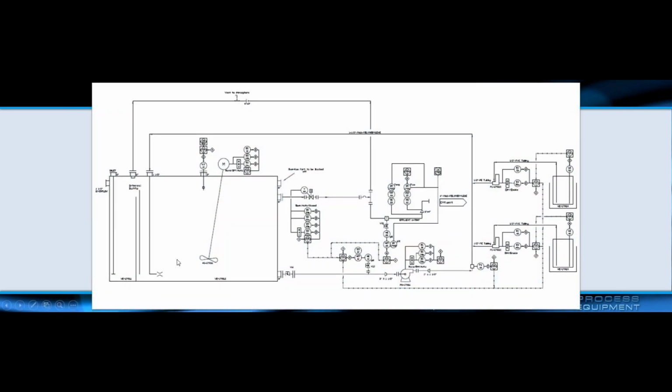Looking at a P&ID here, waste comes in. Sometimes you have a small equalization area in these treatment tanks separated by an over-under baffle. That's not always a requirement. Some people like it as a feature. This goes into your primary treatment tank. Again, this can be a 2-stage system here where you have your double U-trap. This is your standard effluent.